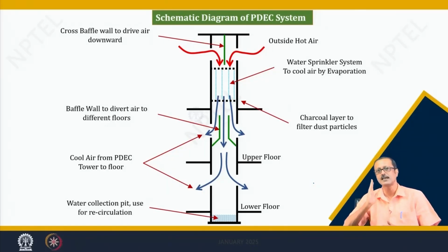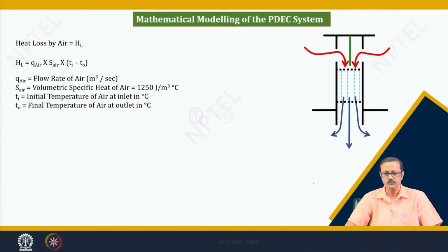It can be applicable only where evaporative systems are applicable, that means in climatic zones like hot and dry climate. Particularly in the desert climate, it will be very good to provide, and it will be very efficient in those kinds of desert climate. You will get a very high value of COP there, and you will get very cool air, and that will definitely help the indoors.